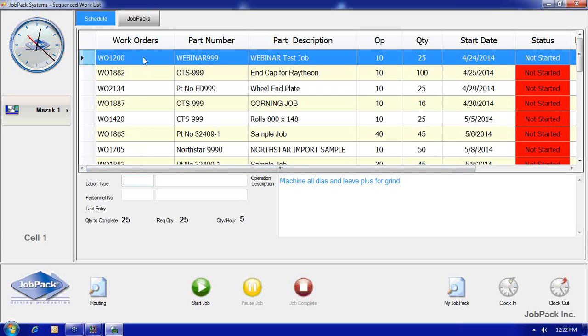We've also got a traveler that we can use with barcodes, but we stopped using barcodes around about 2 years ago. Found that first of all it's not an active work list, and if you change a machine you have to reprint the router or the traveler. So these active work lists are a much more efficient way to get information down to the operator.